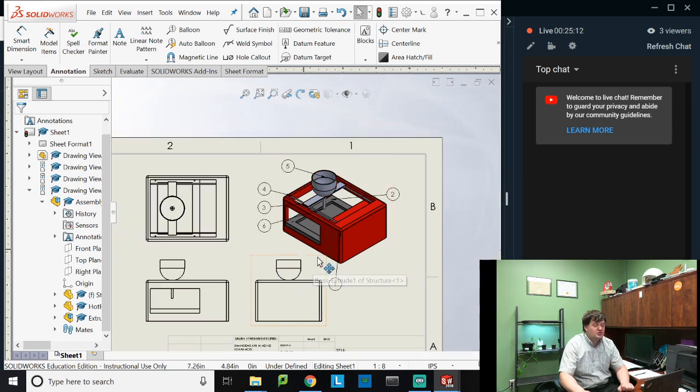In a professional drawing, you need to label what parts are what. Your first page, what I will expect out of you, because I want you to do this right, is your first page should show the assembly. And on your assembly, you should have bubbles or balloons that show what parts are what. If you're doing this in AutoCAD, you'll have to draw the line, create a circle, write a letter in there. You'll have to do it manually because AutoCAD does not import the kind of information that SolidWorks does. Quite frankly, this is far easier in SolidWorks. So I'm sorry to everybody else. But this is generally how your front page would look.